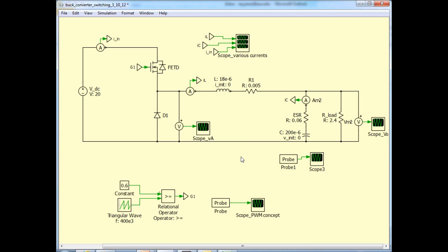Okay, then I also wanted to show a simulation corresponding to a slightly different design. So we are going to use a different design of the output capacitor. If you recall, I mentioned that for the output capacitor we could use either a film capacitor or MLCC, which is a multi-layered ceramic capacitor, and both of these have almost negligible ESR, and so therefore we could use low value capacitance and still meet the delta Vo ripple specification. So let's do a simulation and see how that performs.